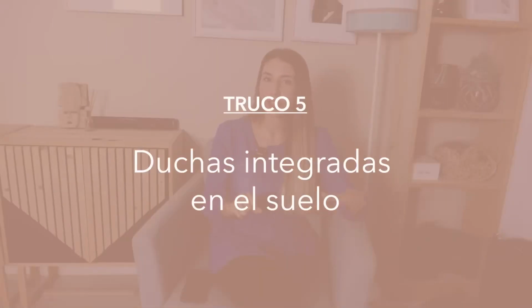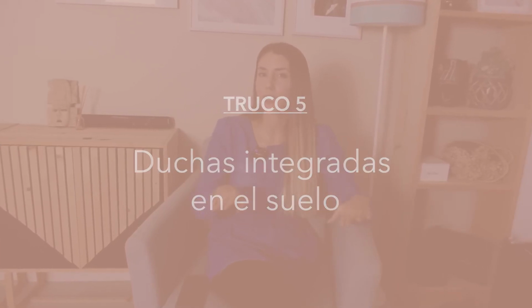The next point would be showers that are integrated into the floor, meaning showers that are at the same level as the floor. Often the same tile used for the rest of the floor is used inside the shower, but what's the problem with that? Could the floor tile be slippery inside the shower? We could solve this easily since there are sprays you can use, and they create a film on top and the tile stops being slippery.